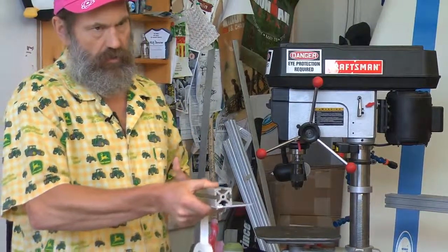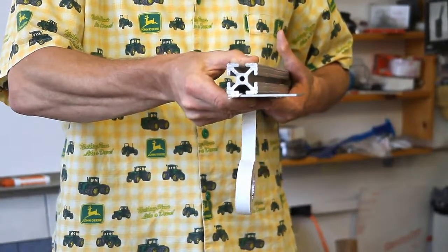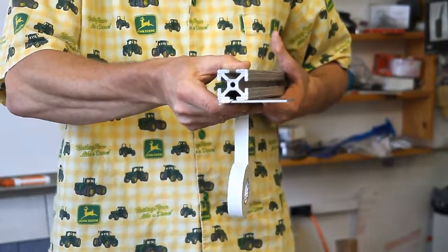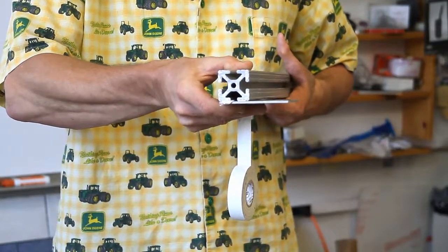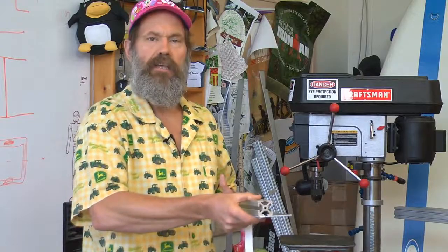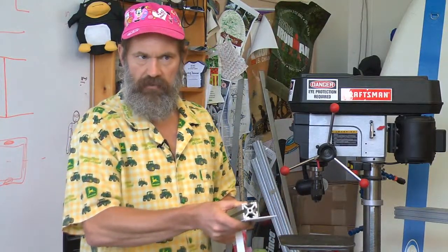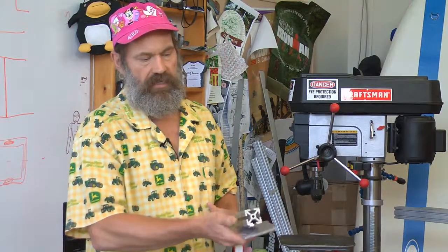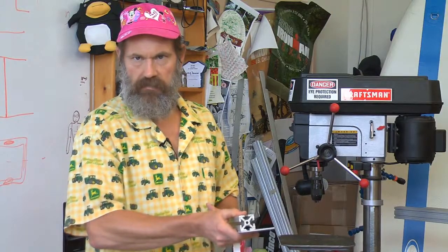So you would close the section. The tape would give you immense stiffness now with the plate you've added. Plus, the tape is a little bit soft and goopy, not too much, still getting very high stiffness. Yet the softness would also provide damping. So you could get a fair amount of damping from your machine by adding a plate with double-sided tape to these open modular sections.